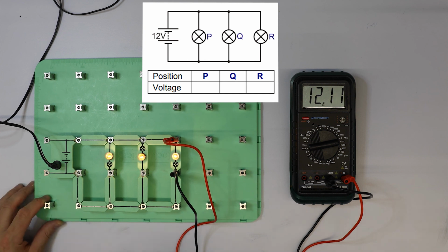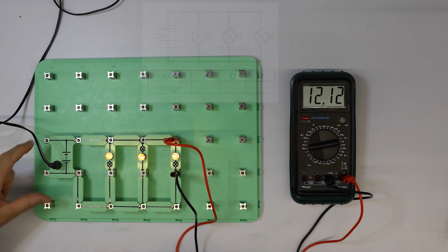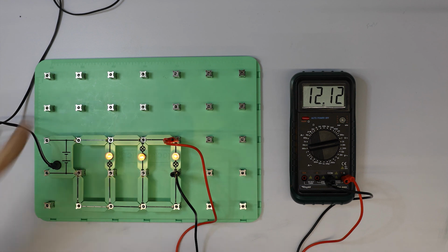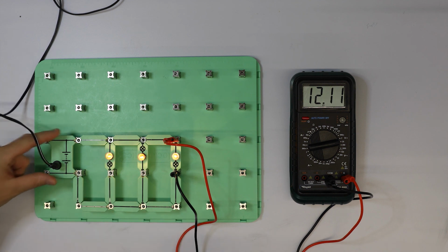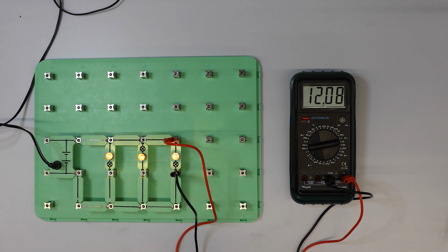So basically what we've seen here is that if we connect all the bulbs in series, then that voltage is kind of divided evenly between each one of the bulbs in the circuit. However, here, by connecting this voltage directly across the lamps, then we see a voltage across each one of the lamps that's equal to the power supply that's supplying the circuit. Okay, so we know that the current is reduced, but the voltage is the same across the circuit here. So that's an interesting result.